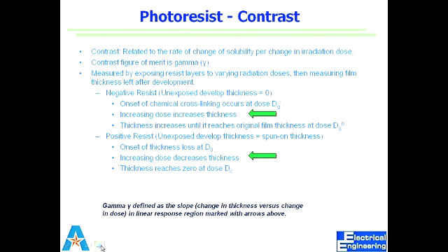In case of positive resist, the areas that are exposed become soluble, right? So they are basically changing into something that will go away. In case of negative resist, they are cross-linking, and the resist part that becomes exposed becomes what?